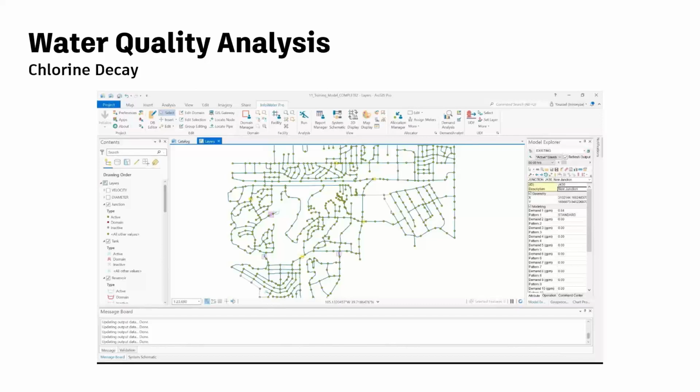This is the flexibility that you get with doing hydraulic modeling. You don't have to do things in the field first. It's actually the model that comes first. As long as it's calibrated, you can use it to do all these analyses before you let your operations crew know what we're going to do, before you invest financially into having your operations crew do it out in the field.